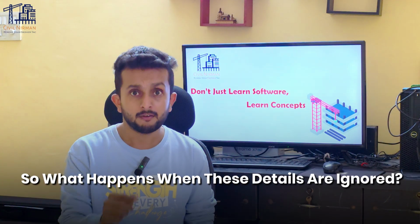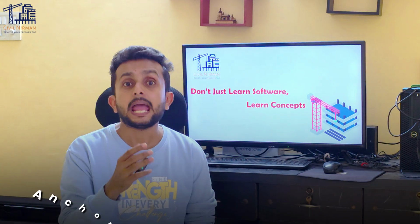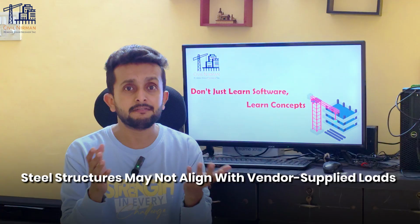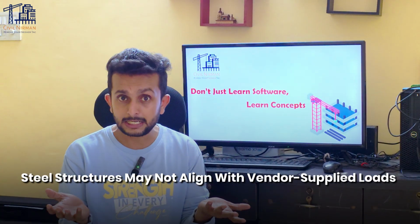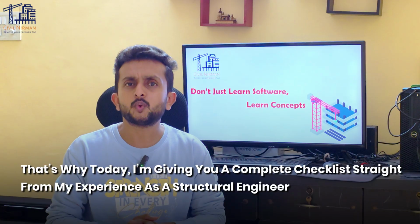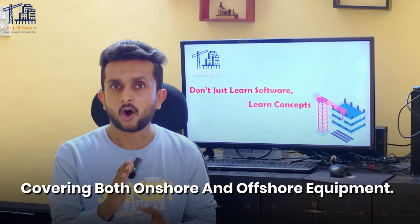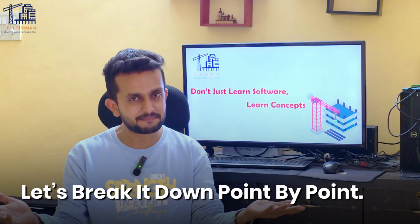So what happens when these details are ignored? Foundation may be under-designed, anchor bolts may clash or fail. Your steel structural framing may not align with the vendor supplied frame, or it may not align with the vendor supplied loads. That's why today I am giving you a complete checklist straight from my experience as a structural engineer, covering both onshore and offshore equipment. So let's break it down point by point.